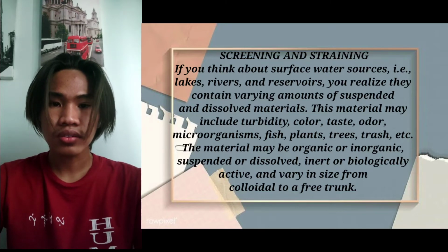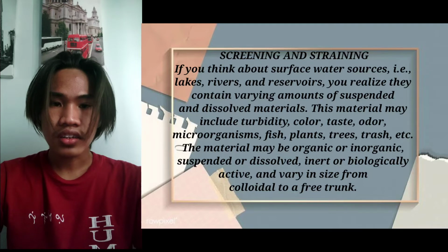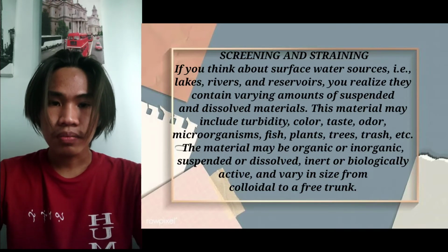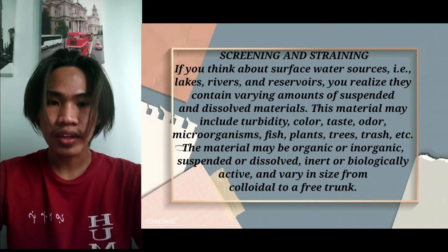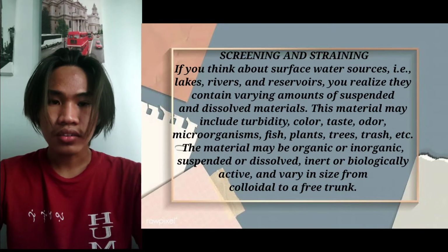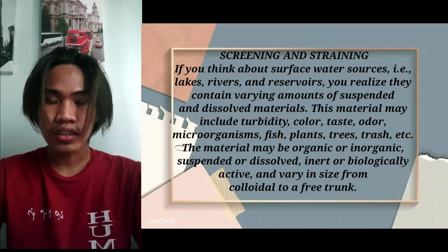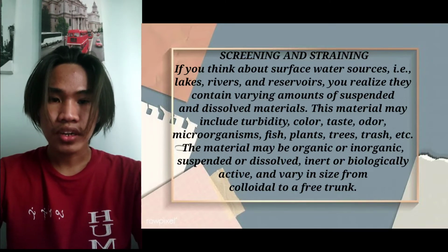The materials may include turbidity, color, taste, odor, microorganisms, fish, plants, trees, trash, and etc. The material may be organic or inorganic, suspended or dissolved, inert or biologically active, and vary in size from colloidal to boulder-sized rock. Some of these larger items can impede equipment in the treatment process, such as debris getting stuck in a water pump impeller.